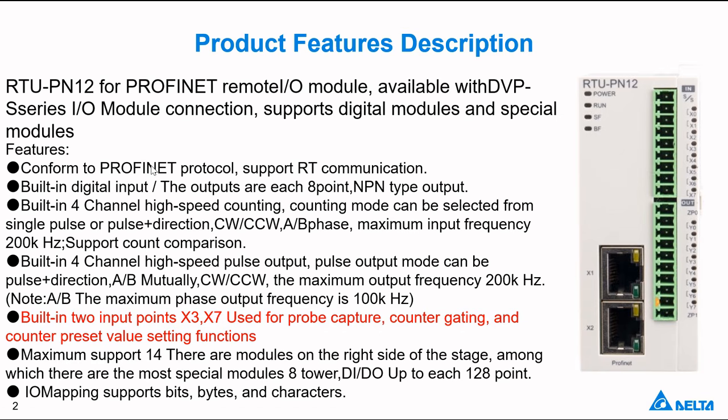remote module, and it supports RT communication, real-time communications. It has built-in 8 digital inputs and 8 digital outputs, for the NPN type. It also has 4 channels of high-speed counting and 4 channels of high-speed pulse output.